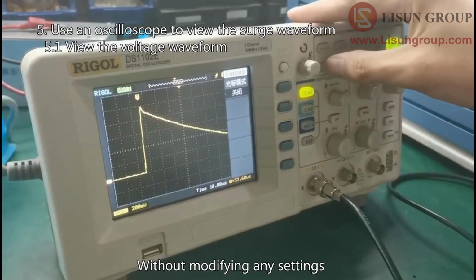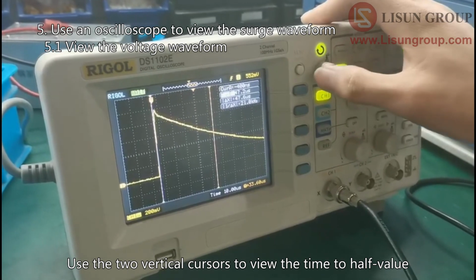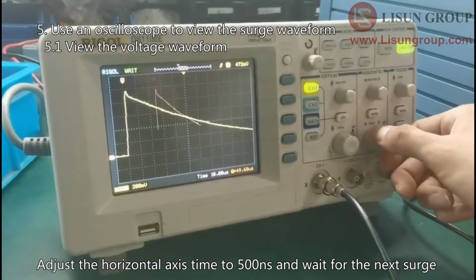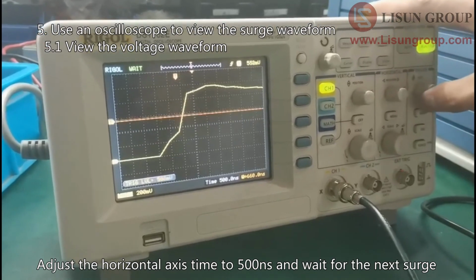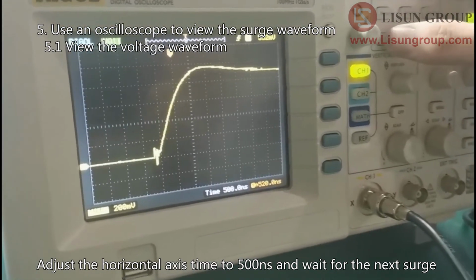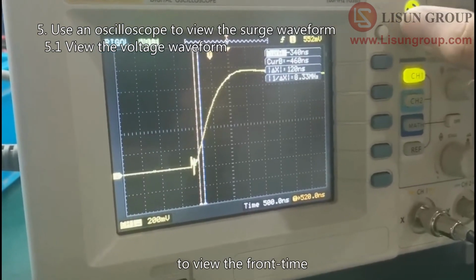Without modifying any settings, use the two vertical cursors to view the time to half value. Adjust the horizontal axis time to 500 nanoseconds and wait for the next surge. Set the two vertical cursors from 30% to 90% of the surge voltage to view the front time.